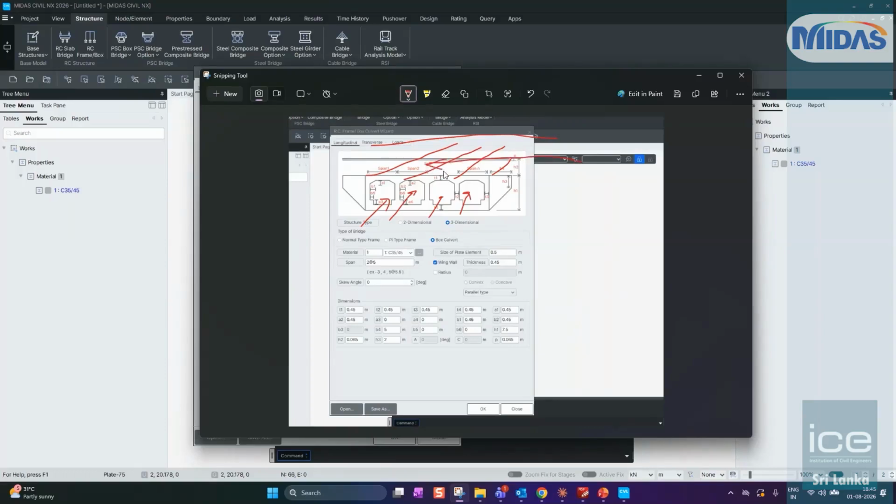So this is the direction of the moving traffic and this is the direction of the water stream. Generally you will have water, but sometimes it might be the case that on the upper level you have traffic movement in this direction of the box culvert. However, at the bottom floor you can have traffic movement in the orthogonal direction, in the direction in which the stream flows. So it is very much possible. In case you have different utilizations, you must always bring in considerations based on those particular utilizations.